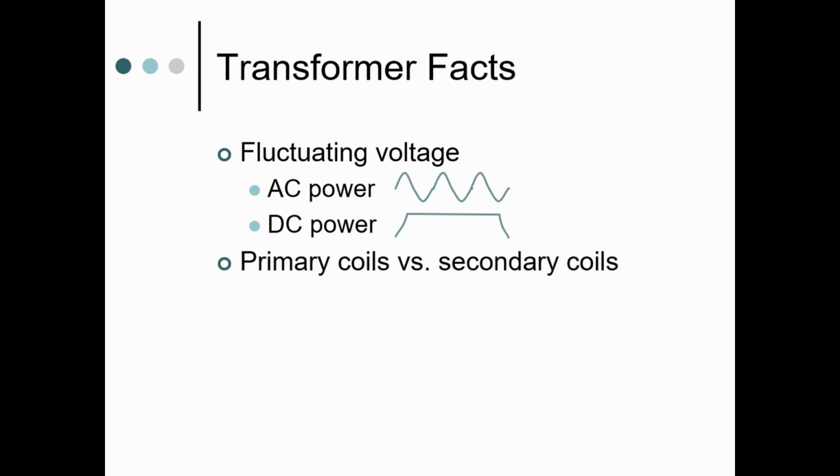The primary use of a transformer is to change voltage in a circuit, either up or down. If a transformer has more coils in the secondary than the primary, it will increase the voltage in proportion to the ratio of coils. This is how an X-ray machine can have an input voltage of 120 volts and then provide a voltage of 70,000 volts for powering the X-ray tube.